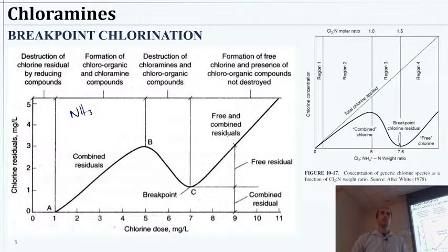So it could be NH3 by itself. It could be some organoamine that has NH2 or 3 in it. And then that's being chlorinated, so to speak. We're adding chlorines to it, making these substitutions. And we are getting some of these disinfection byproducts. During this phase, the more chlorine we add, the more we get because we're forming more of these combined chlorine compounds. It's not going to be necessarily linear.